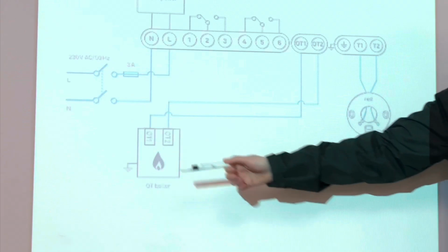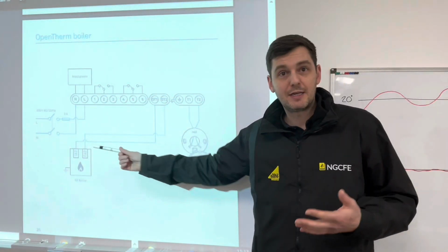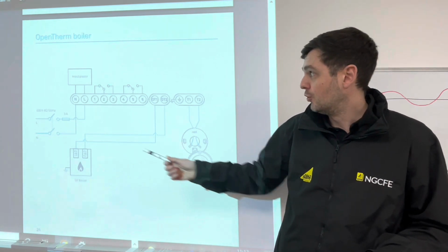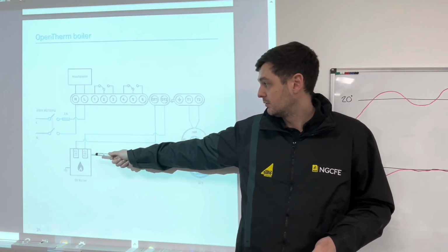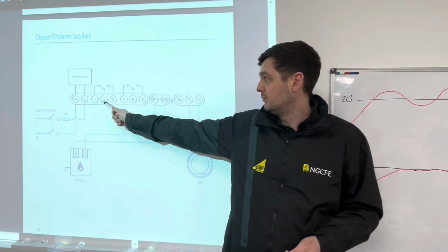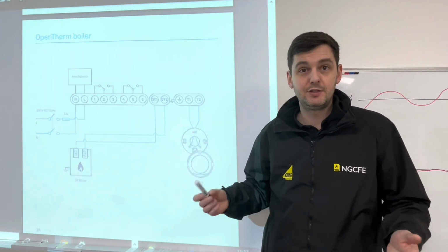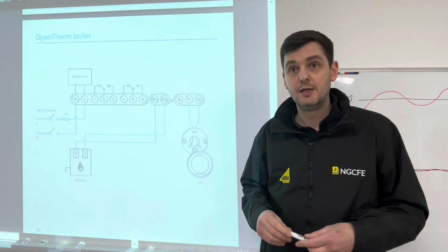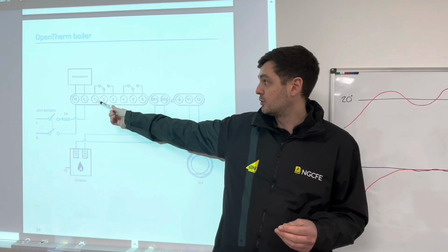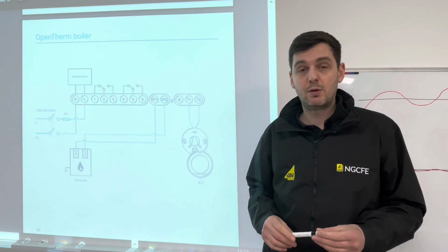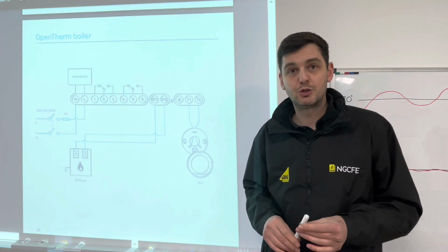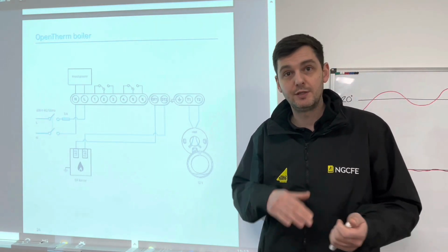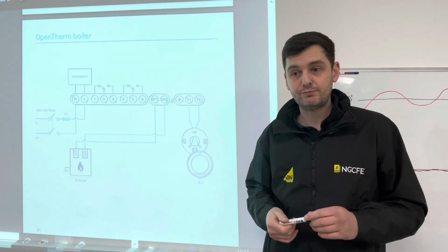Now these say OpenTherm, but imagine that they don't. Imagine they are the thermostat connections if you want 230 volt or low voltage, whatever it may be. Normally we would be taking these two wires to terminals 1 and 2 for a standard control, standard efficiency, and that's basically what our old controls, the on-off controls are. So wiring a control to 1 and 2 will probably give you, unless the boiler's quite smart, the same issue that we spoke about at the start, where you might overshoot your temperature and undershoot.